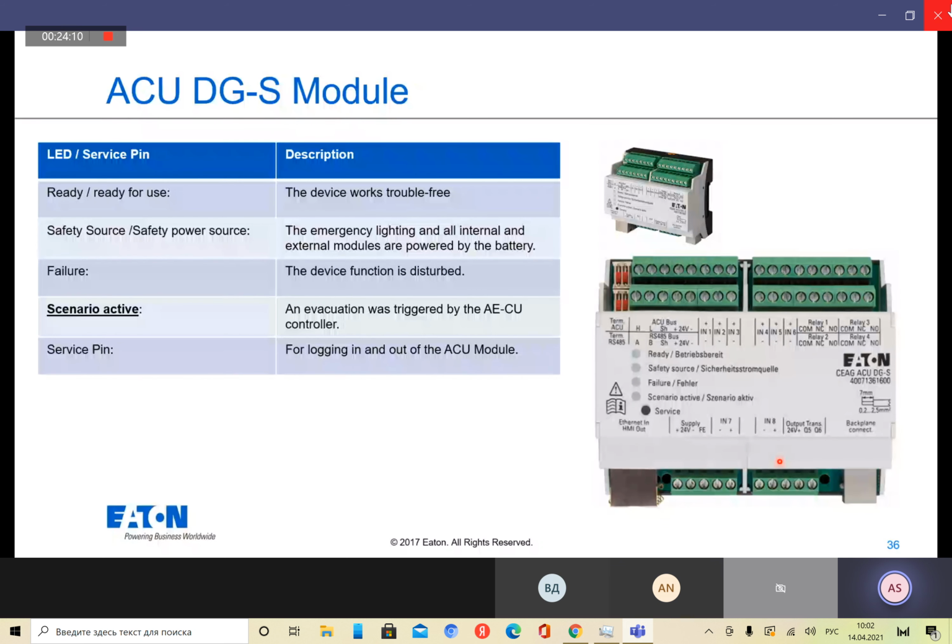I just missed one thing. The RS485 bus is still the same, right? The length is still 1200 meters and 120 ohm. The ACU bus has 120 ohm as well. It's not very important because you have the internal resistor, so you don't need a separate resistor, just for your information. So 120 ohm and 900 meters. So it's the same length we had in the CGS bus. Okay.